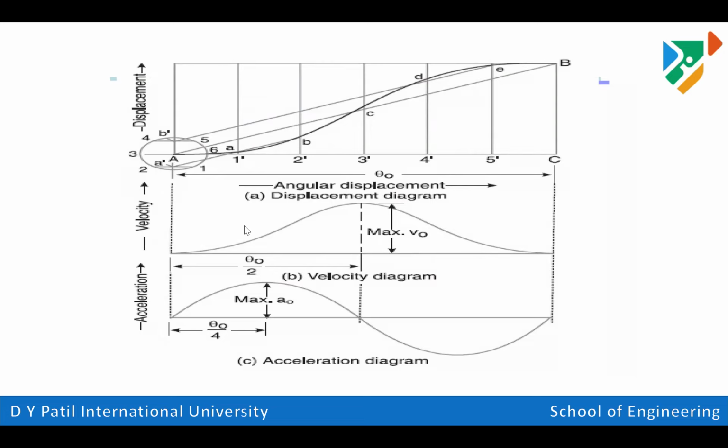first we need to draw the circle. Now how to draw the circle? To create the circle, what we have is the circumference, which is known. S is 2 pi into r. This is the circumference value for the circle. So the radius of the circle is equal to the lift of the follower s upon 2 pi. I will simply explain how to create that radius.